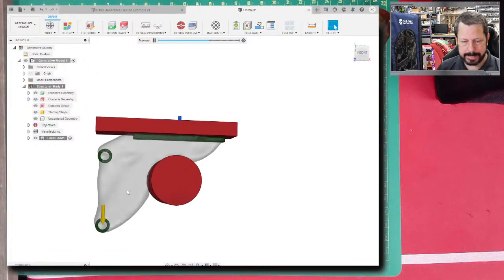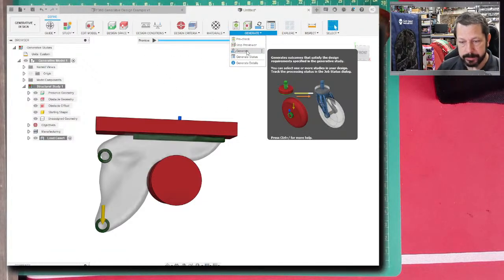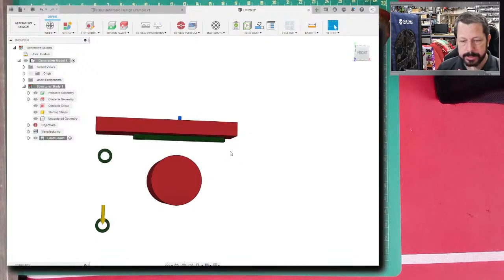So, that's the shape that we can expect from this thing. It'll probably be eaten away more than this, but I do have it creating a factor of safety of 4 and a 200 Newton load on this thing, and it's not that big. This bar across the top was only 10 centimeters, so it's like a 6-inch bracket or so by the time you add from here to the end. So that looks all right. And then we go to generate. Yes, we're going to stop the previewer.